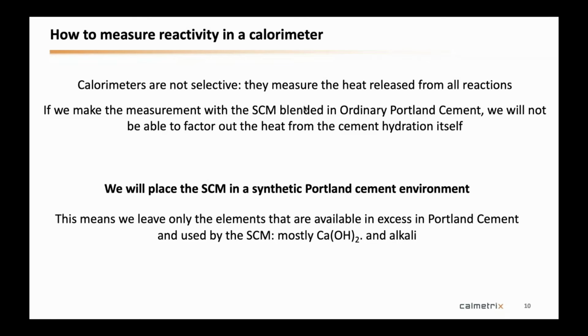And to separate them out, we have to get rid of all the Portland things. So everything that's related to Portland cement hydration, we have to get out. So we will actually not use a true Portland cement when we test for reactivity of an SCM. We will use what we call the synthetic Portland cement environment.